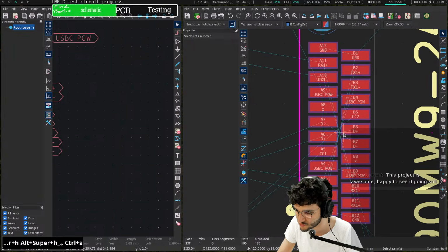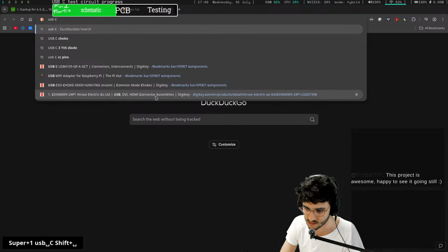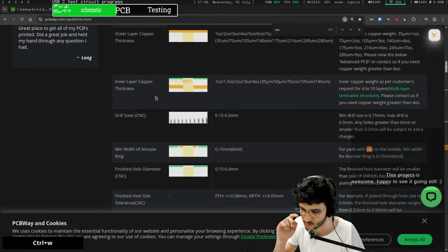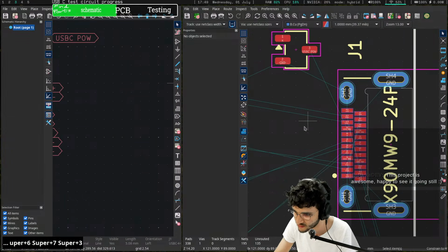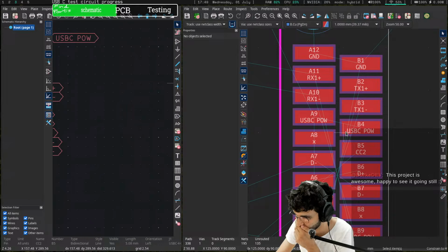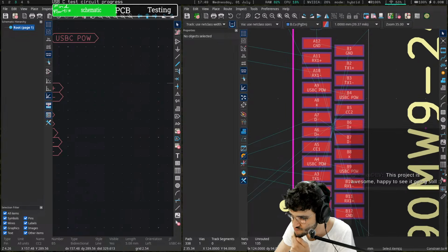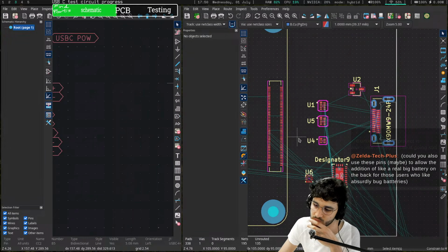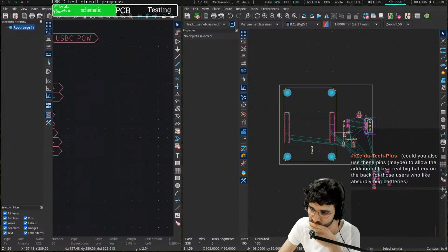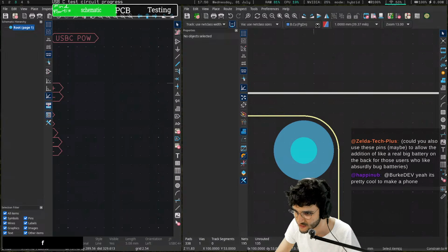I think I want to see USB-C. Okay, whatever. No. I think first we should route the most complicated pins, which are the signal lines, the TX and RX lines. And they will be going on the outer layer. I mean, the layer that's called front. The red layer.